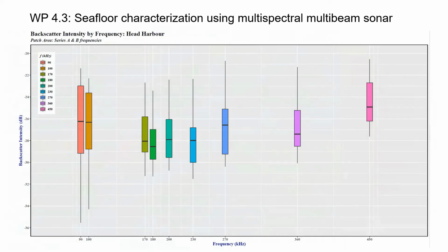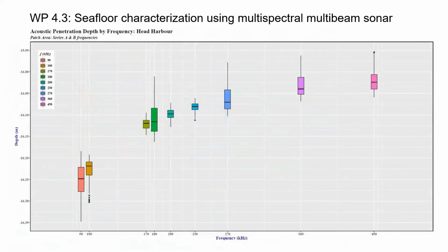Backscatter across all these different operating frequencies over this smaller site in the middle is roughly the same, probably about a 2 dB difference, and we need to do a little bit more work with the data. What was interesting was looking at the bathymetric surfaces generated from that mud location by frequency. We see a really interesting trend across those operating frequencies by comparing the depths. Quite a nice response there in terms of penetration depth.